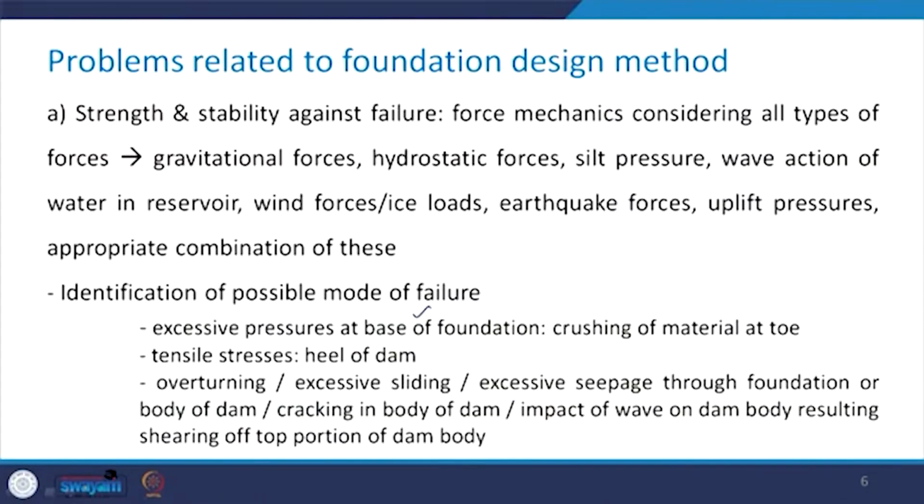The identification of possible modes of failure becomes very, very important. Now, how can these occur? There can be excessive pressure at the base of the foundation and that can result in the crushing of material at the toe. There can be the occurrence of tensile stresses at the heel of the dam, or there can be overturning, excessive sliding, excessive seepage through the foundation or the body of the dam.